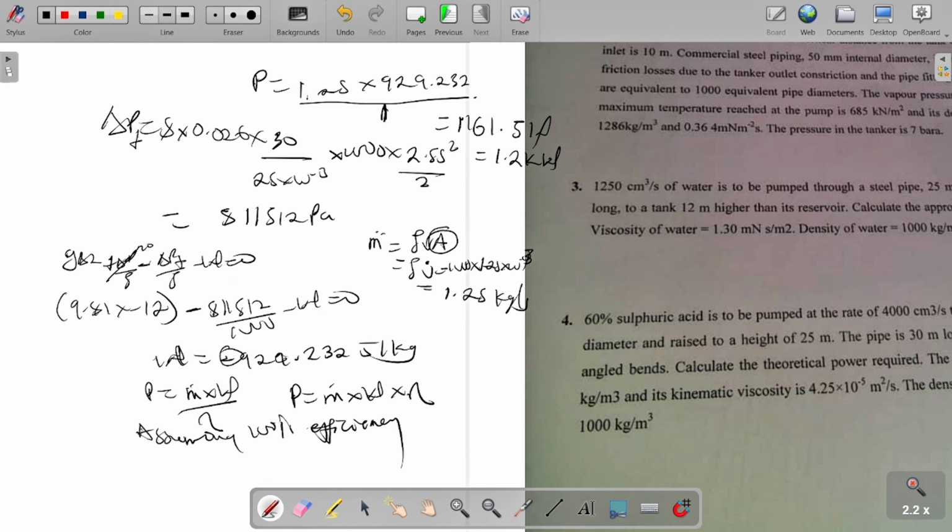So this is how to solve for the power for this question. It's very easy, and please make sure you don't make any mistake with your change in z, because that's where everything can go wrong. If the change in z is supposed to be negative and you make it positive, you actually get a negative answer for W, like negative 600 and something, but it's wrong, because the change in z is z1 minus z2, so it's supposed to be negative. Do you get it? Okay, sure.